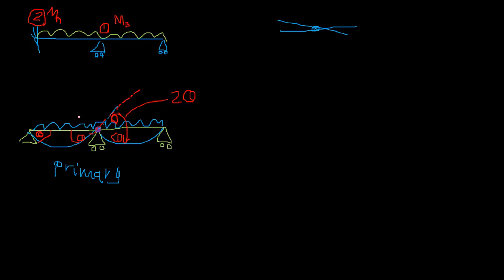It doesn't matter. Why are we taking displacement? Because we are in the force method and we should work with the compatibility. That means the shape of the structure. In the original structure, the relative rotation here is 0, and here also the rotation is 0, right? Here you have now made it 2 theta and theta. So this no longer remains the original.